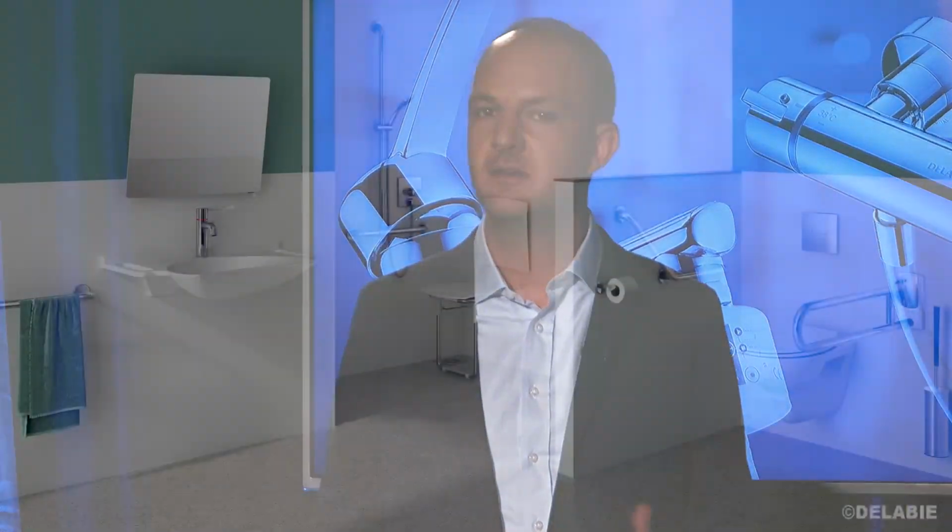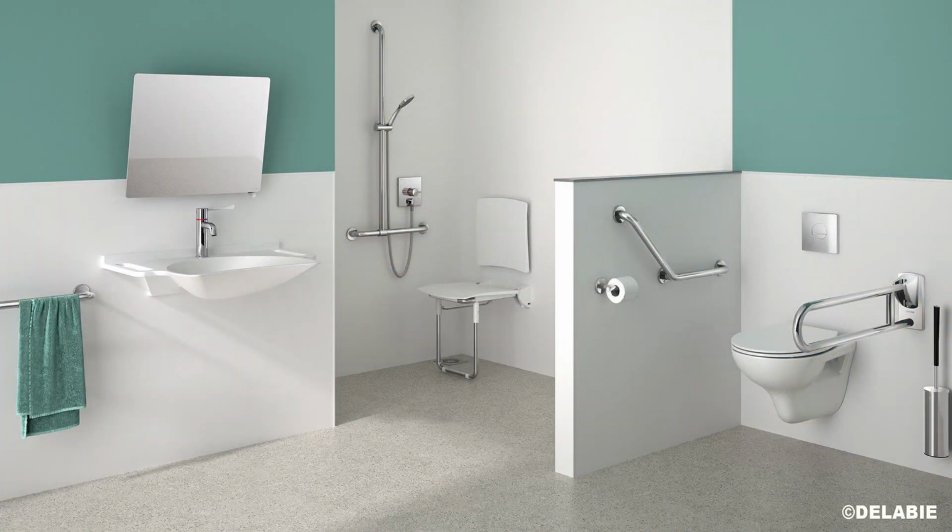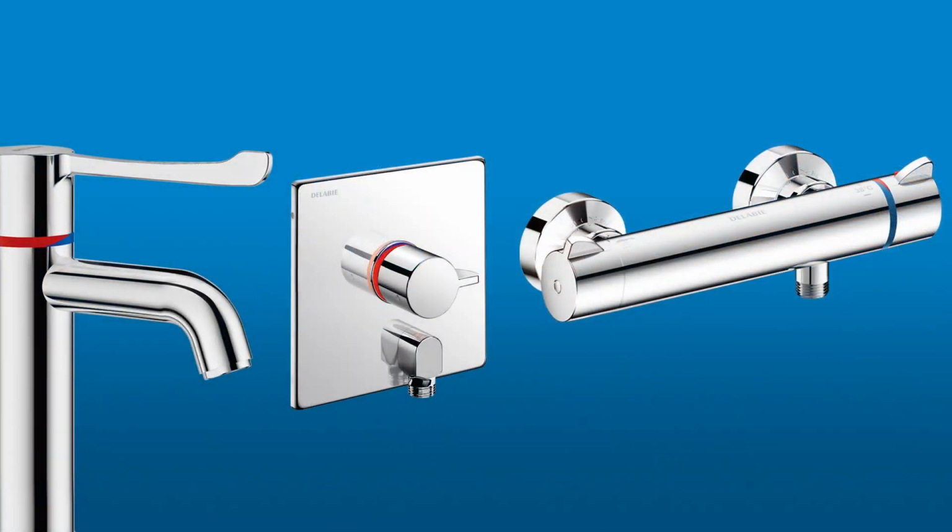So if we take the example of a hospital with 200 rooms, each with a basin mixer and shower mixer installed, it means 800 non-return valves that need to be checked every year. So realistically, this is almost impossible. That's why we are offering solutions without non-return valves and with a unique system, which means that the hot and cold water supplies can be shut off upstream of the mixing chamber.